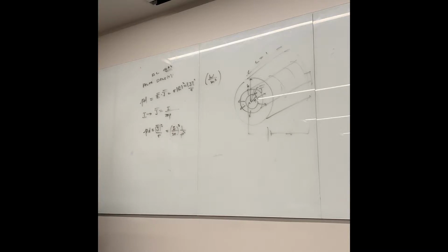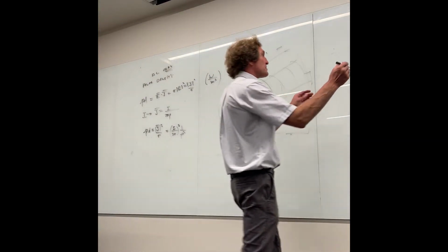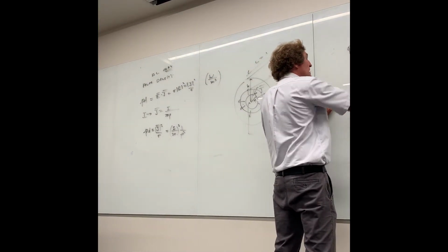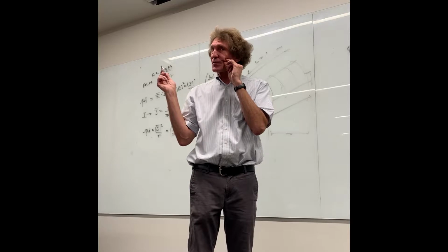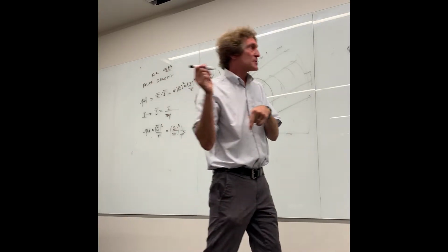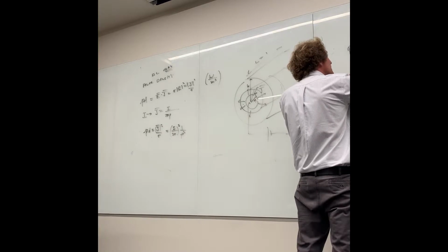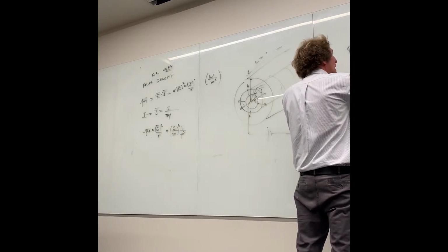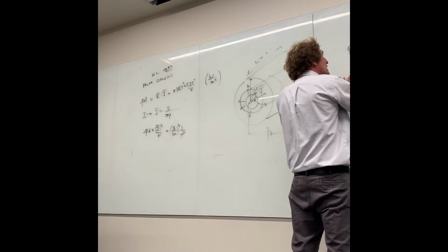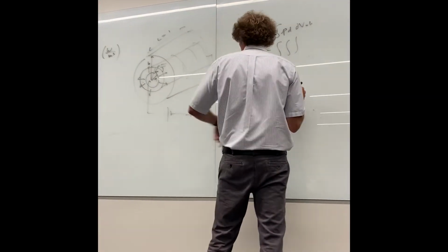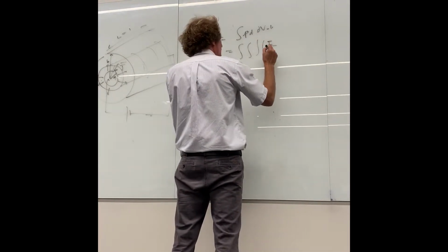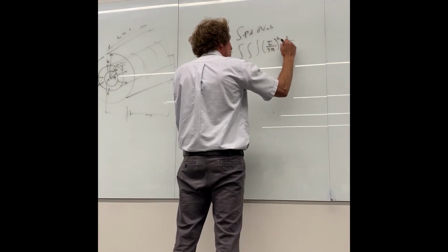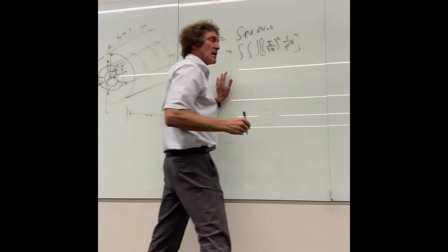Everybody see this? Now, once I have the power density, how do I get the total power? Total power, not multiply, integrate through. That's real important. Well, that's a power density, it's a function of rho, see that? So now you have to do the integration. Total power would be equal to the integral of the power density over the volume. Well, that's a triple integral. So first you put in your power density, which is I over 2 pi squared times 1 over rho squared. Now we need a differential.